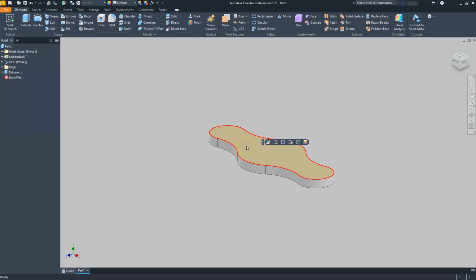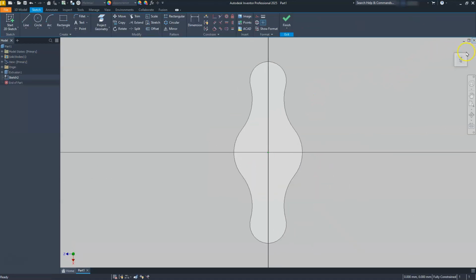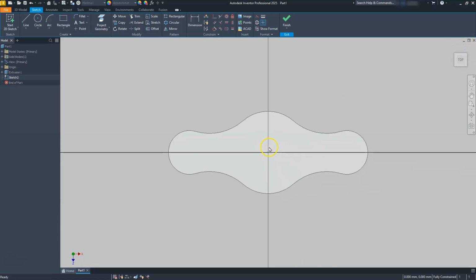In the AutoCAD video, I did put it at the bottom here and extrude up, but it'll be the exact same steps and principles. Go ahead and select this top face, and then go ahead and select this icon here, which says Create Sketch. It's the one with the green plus. Let me go ahead and rotate this back. Next, I want to go ahead and place a couple of circles on here, right?